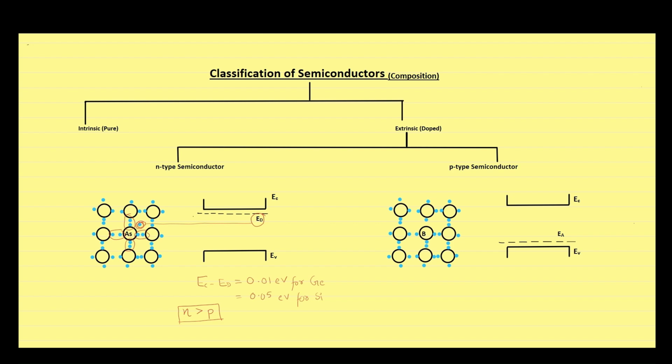As you can see, in the group of atoms shown under the p-type semiconductor, the central atom is a trivalent impurity, taken here to be boron, and the nearby atoms are silicon. Boron shares 3 of its electrons with nearby silicon atoms, but here we have a hole. When a nearby electron moves to this vacant site, boron becomes stable. However, another hole is created from where the electron came. This procedure keeps on happening, resulting in hole current in an arbitrary direction.